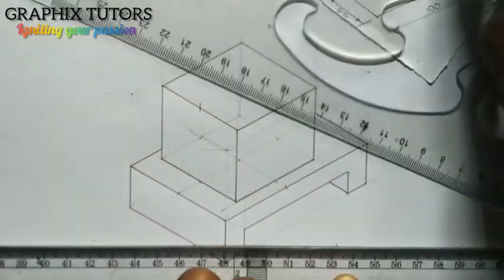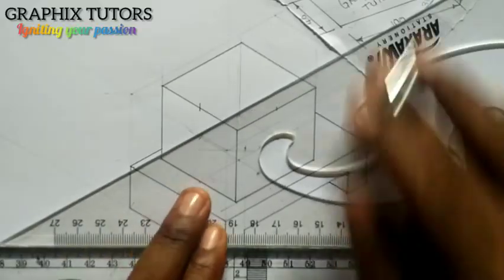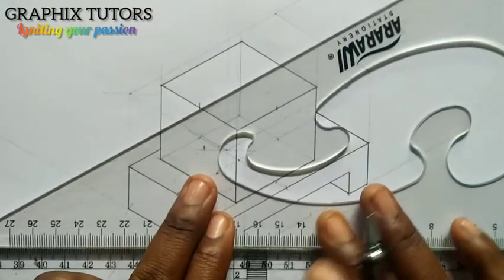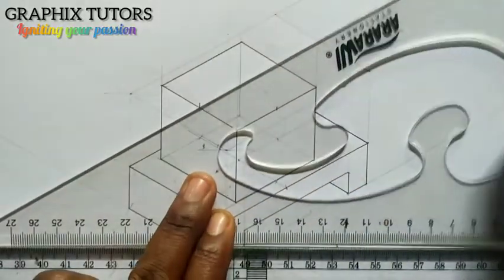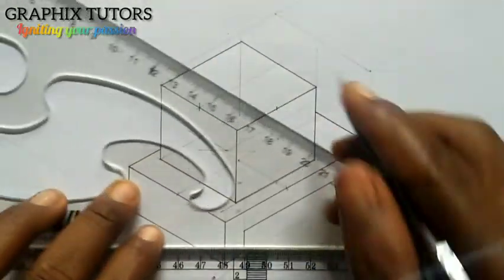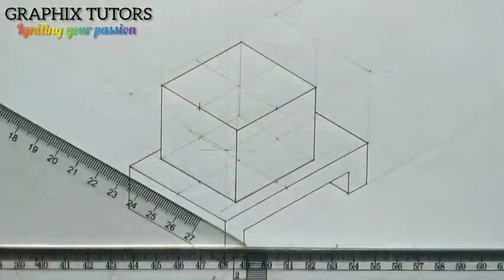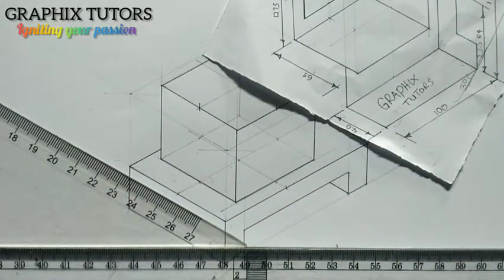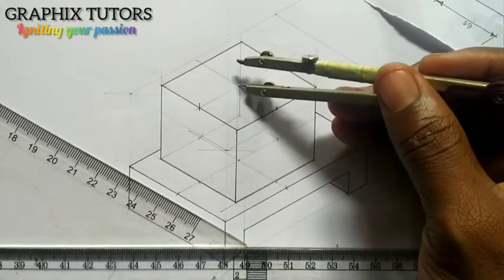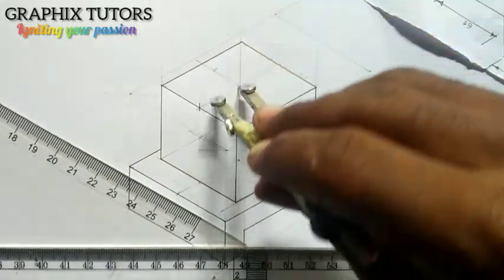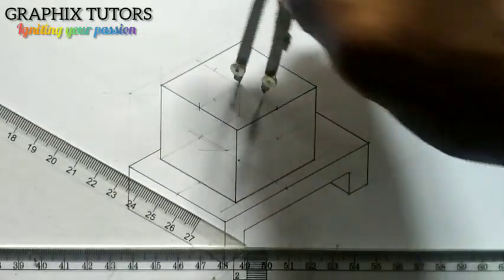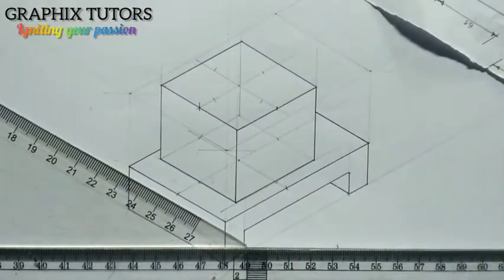So I'll just place my set square on my T square. I'll just draw my horizontal line, as in my faint line, just a faint line like this, and I'll turn it this way again. I'll draw my faint line like this. So this is where they meet, so that will be my center, right? So I'm going to measure half of 50, which is 25. So I measure my 25, right? So I'll be having this. I'll place at the center here, and I'll mark 25 here, 25 here, 25 here, and 25 here. So I'll be having this.